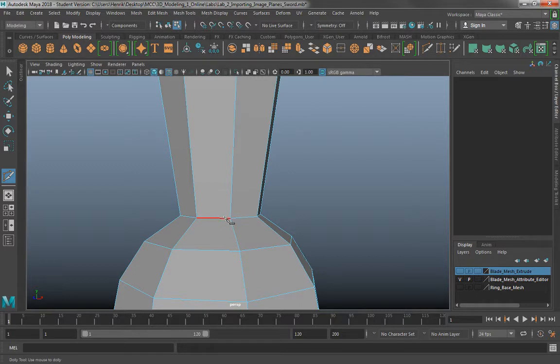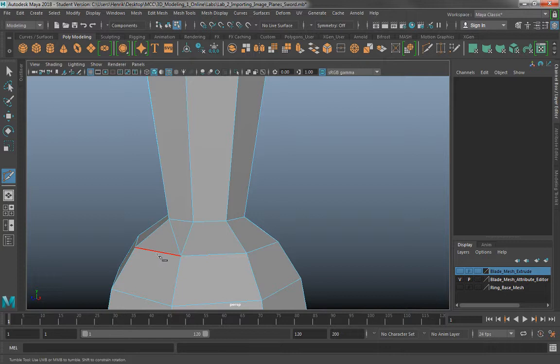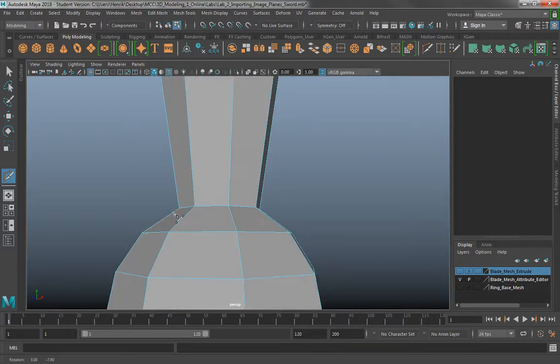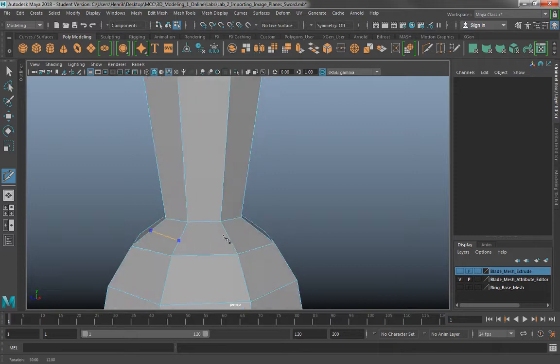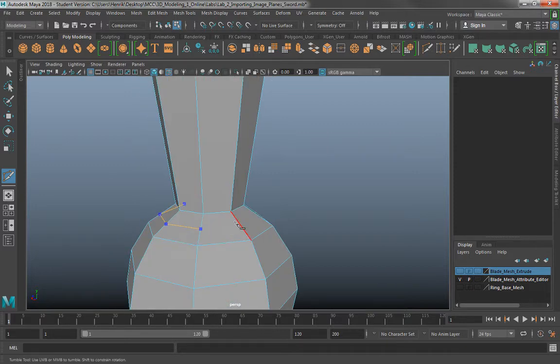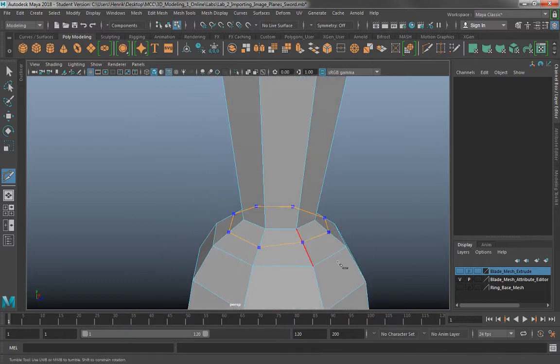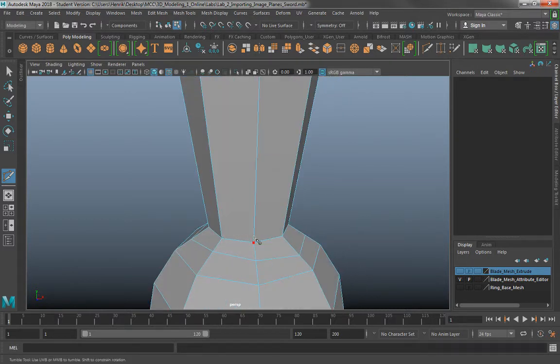So let's just pretend, I'm going to show you one example for once. You can make custom cuts into your geometry. Typically, you always want to go vertex to vertex. Sometimes not, but in this case, I'm just going to show you one way, because in one of our first videos, I spoke to you about triangles and how the software reads triangles. So that's one way to custom cut in your geometry. You can also, let's just say I want to go around here and do some hands-on custom cut throughout my entire mesh. I can do it this way too. And then when it says close here, which I already clicked on, and then I press enter, it makes that cut, and that cut's finalized.